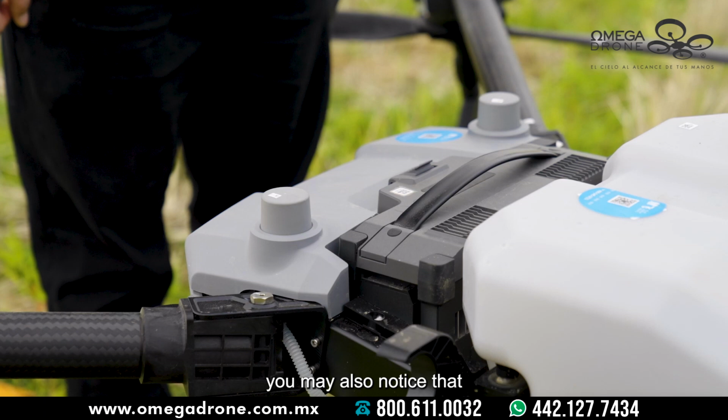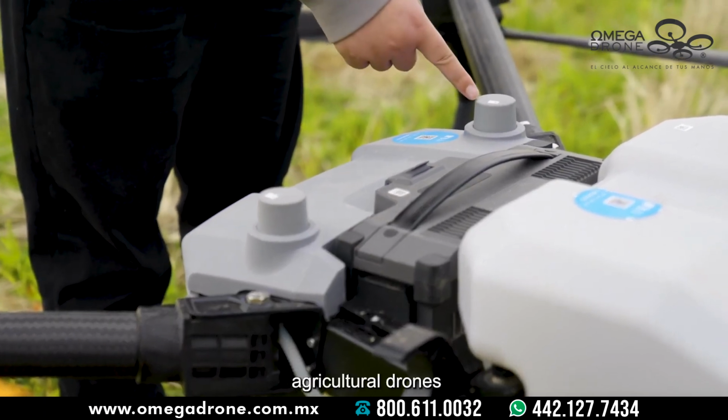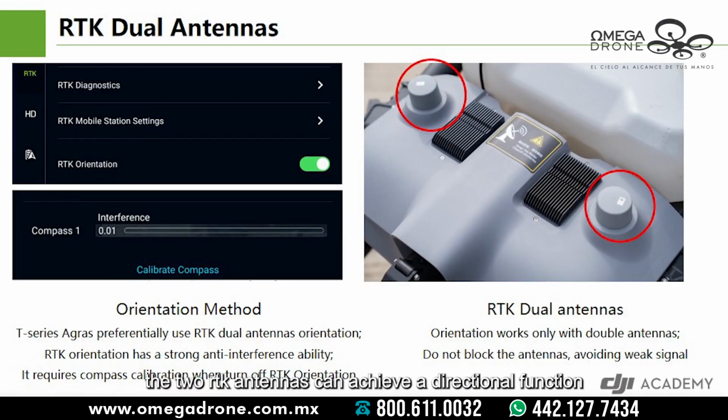You may also notice that there are two mushroom-shaped heads on the T-Series agricultural drones, which are RTK antennas. The two RTK antennas can achieve a directional function, which is somewhat similar to the compass, to improve the flight accuracy of the drone and the ability to resist electromagnetic interference. If there is no RTK orientation function, the drone can only be oriented by the compass. So, if the RTK orientation is turned off, be sure to calibrate the compass.